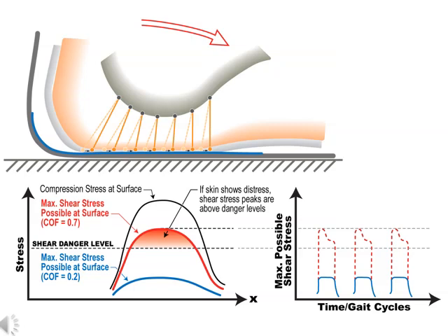In spite of Naylor and Sulzberger's experiments, it may still be unclear to many why shear loads are so important. Experimental mechanics experiments reveal that even solid materials like metals tend to fracture along planes of maximum shear stress. Shear superimposed on compression creates dramatic distortion. Repetitions of these distortional stresses will initiate microfractures. If there isn't sufficient time for biological repair, damage accumulates.